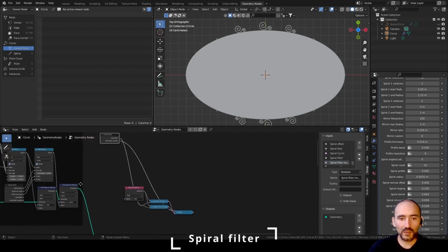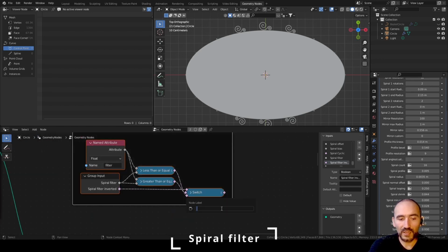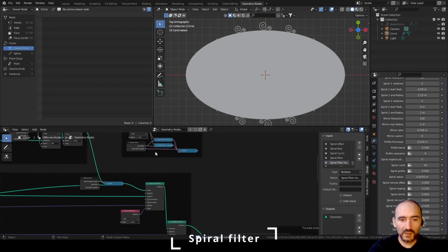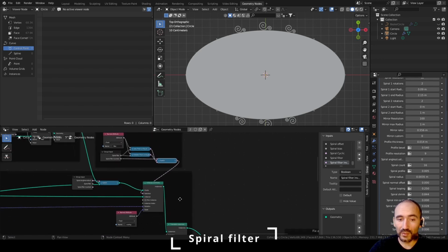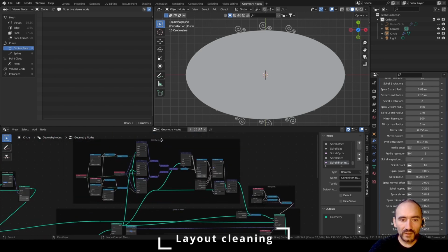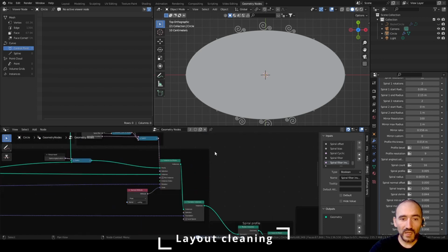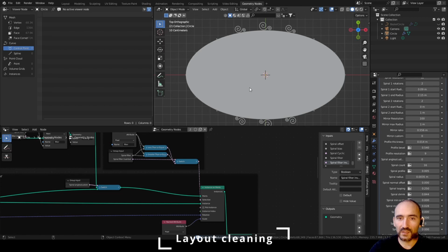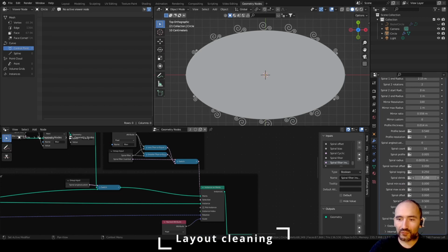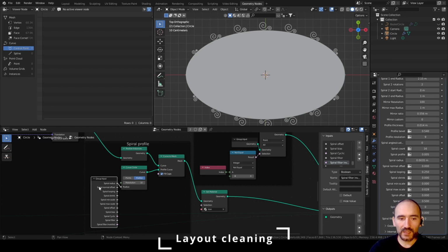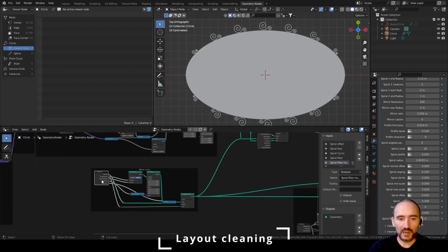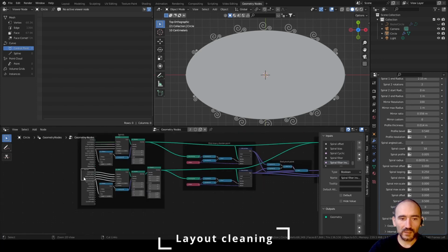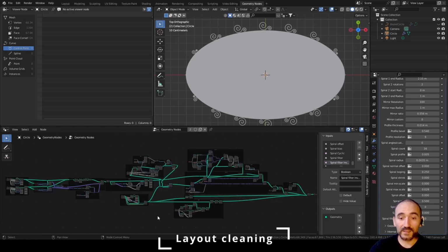Ctrl H to this node, we can select all these nodes, Ctrl J F2 filter points, and now we can easily link this switch in the selection of the instance on point node. We can play with the position of this layout a little bit, and now we have all the nodes we need to play with this environment. So we can set the shrink to 0, press Ctrl H twice to hide the attribute not used, and we can press Ctrl H for each of these group nodes in this layout, here, here, here, and in the initial part of this tutorial. And this is the entire workflow.